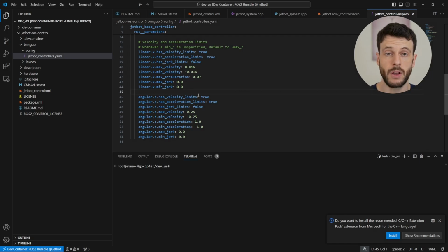And down here is where we can set velocity limits. This is where we can start to configure the controller more to do what we need. We can specify that there's a max velocity to send to the motors and a max velocity that they should turn at. Now these numbers I found through experimentation. Normally, the controller will send units of 1 per second, which you can interpret as radians per second. But for our motors, that doesn't actually correspond to a real-life measurement, because we're going -1 for maximum reverse to +1 maximum forward. That doesn't always map to the same velocity. So instead, we're just going to guess numbers, and there's no feedback mechanism to correct them. So these are just numbers that I've obtained that give a reasonable rate of movement.